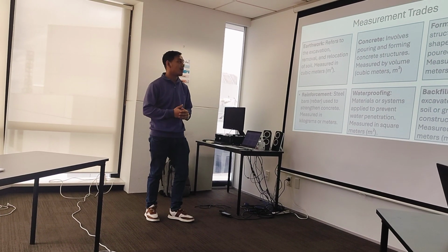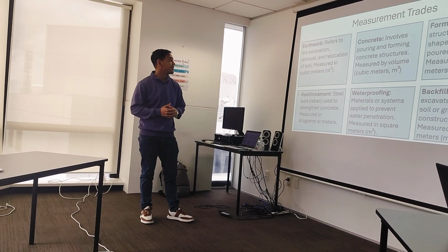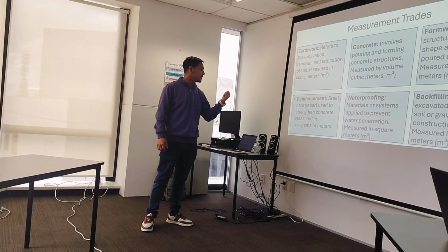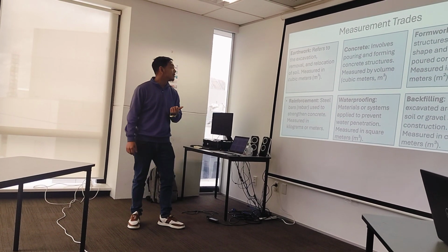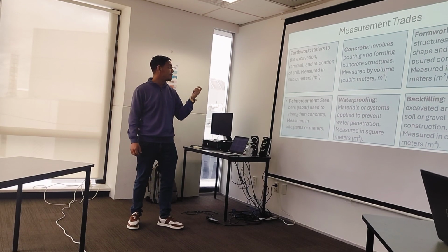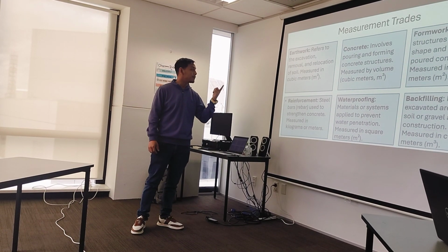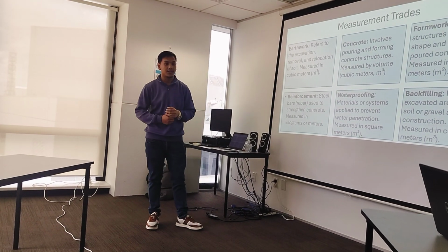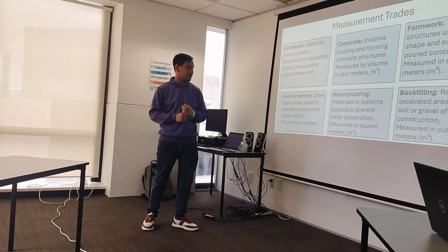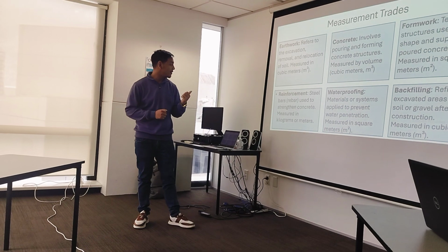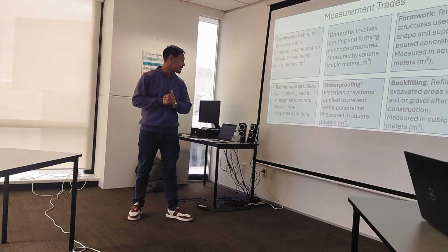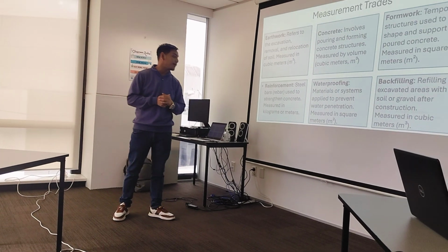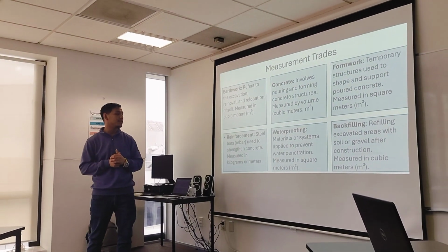So, as per our assignment, the measured items are earthwork, concrete, formwork, reinforcement, waterproofing, and backfilling. Earthwork can be measured in square meters, concrete in cubic meters, formwork in square meters, reinforcement in kilograms or meters, waterproofing in square meters, and backfilling in cubic meters.